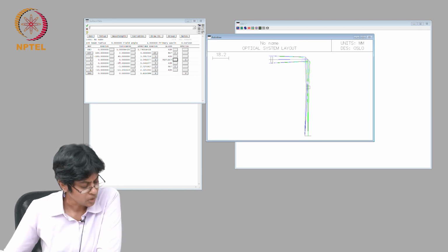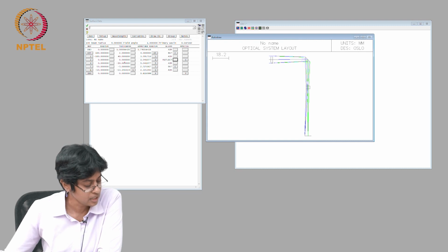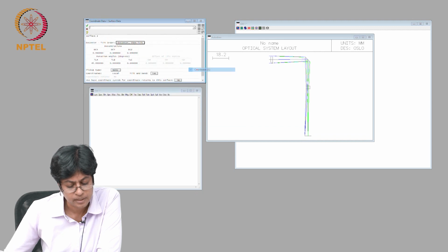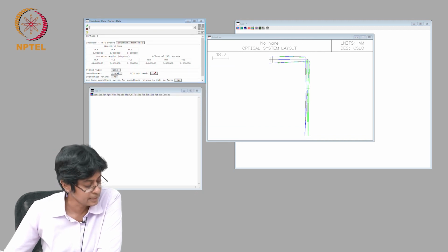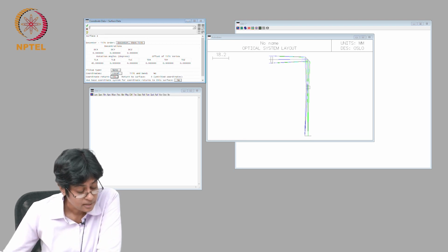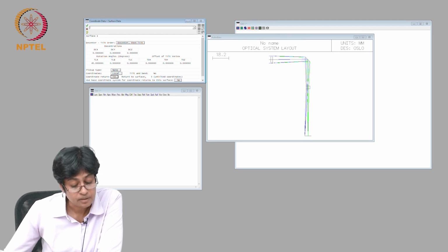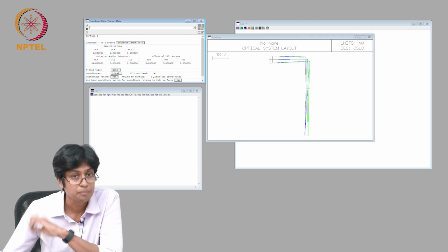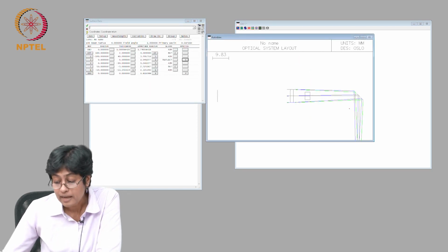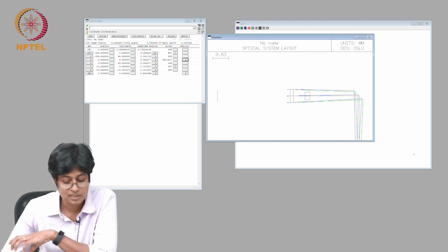Okay, I've added a dummy surface, I've transferred the thickness, and now I'll go back to surface 3 coordinates and I will remove the tilt and bend. I still have the 45 degree angle over here, and one other difference is I'm going to change the coordinate return, make it yes, and I'm going to say return to that surface 3 itself, but the untilted coordinates. Now, since I've done that, I'm in the process of setting up my system.